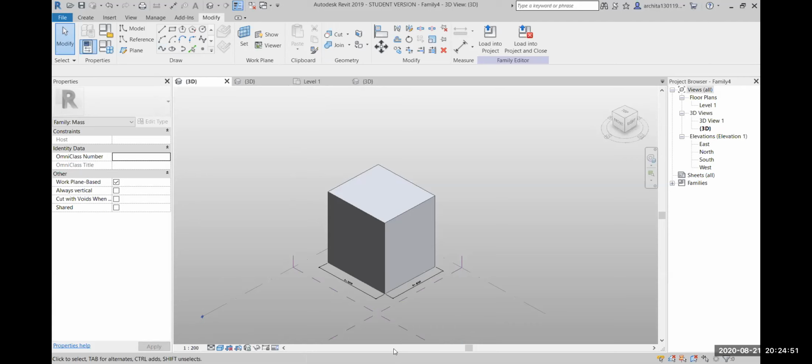So your mask floors got created. Then you have to click on the floor by face option under masking and site, and then create the solid floors. Okay, so I should go for floor by face and then create the solid floors. Yes. Okay, I will practice that and see. I think this is the same thing which you asked in the doubt also, no, guys? I couldn't get the option only that time.